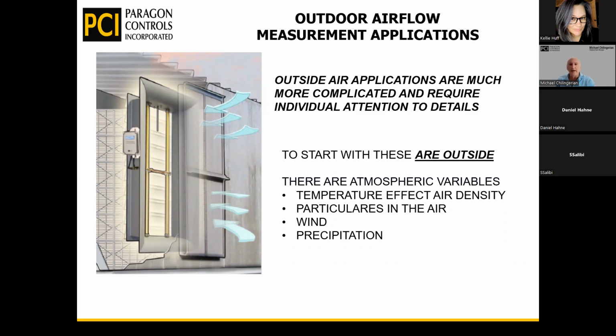Before, we only did airflow measurement because a LEED project said you had to have it. In California, we have Title 24. ASHRAE talked about 62.1. They also talked about 189.1. I should have put that down. Sorry, I forgot to put that down. But those were really the only reasons that we did outside airflow measurement. Other than hospitals or schools, outside airflow measurement wasn't really all that popular in general. But because of COVID,